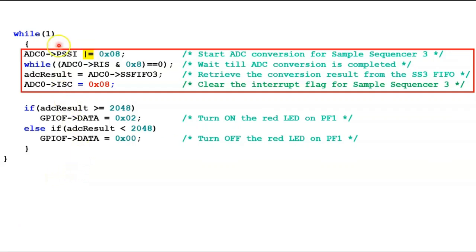Okay, so we are back here. So let's take a look at this operator. This is a bitwise OR with assignment. All right, so the value 0x08, this is 08 hex. If you translate that to binary, that would be 0 0 0 0 1 0 0 0.